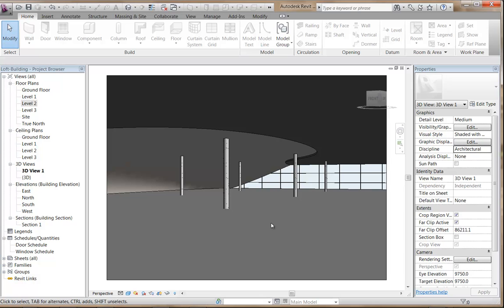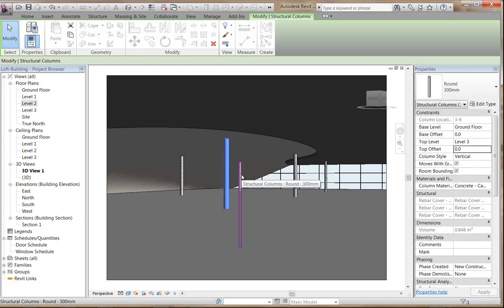It had a lot more detail afterwards, obviously, but one thing I might do here just to make this look a bit more presentable is bring all those columns up that are outside of the void, or they're inside that cutout. So again, top offset there, 3000.